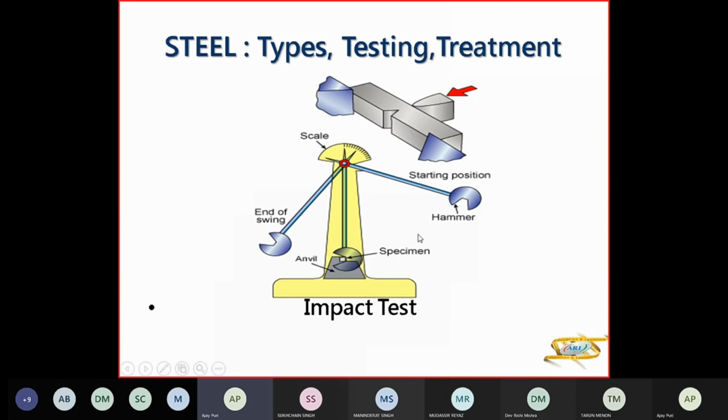We will not go into the specific velocity, because that is not your question. Your only requirement is that potential energy is converted to kinetic energy, hits the specimen, and there's a notch made in the opposite direction of the test piece, and here it hits, and then it will swing out. So then they check for the crack. If it doesn't crack, they raise it higher. So the angle of the height of the pendulum is raised further and then it is hit here. So this is known as Charpy V notch. We are making a V notch of standard size on the various metals.